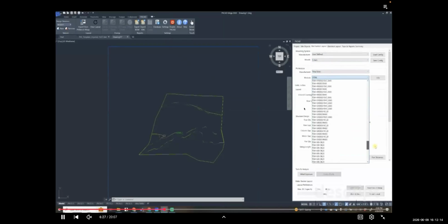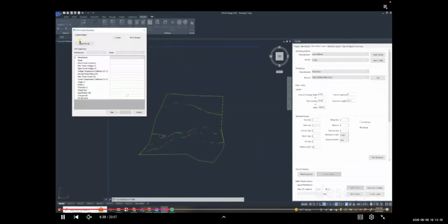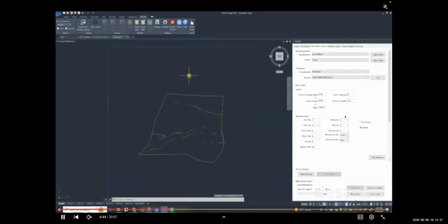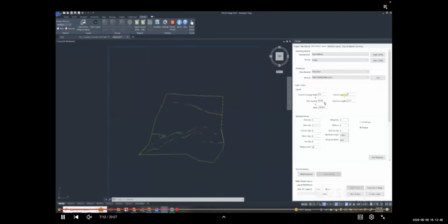So you can adjust your GCR, your row spacing, all of those adjustments that you can do while you're doing these layouts. This is basically where you go in and import your PAN file if you want to upload any module here. Now, all the attributes that you're seeing here, the GCR, and when you change that, so let's say for this design, we changed this to, yeah, these are all the panel properties. And then if you decide to change this to 0.3 GCR, you would see the row spacing and all of that gets adjusted on its own.